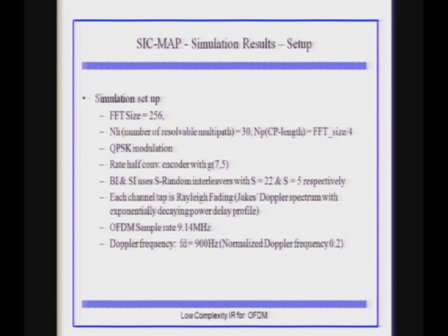And then there is some research that was done on how we can optimize the interleaver so that you can have a balance of the interleaver length and the randomness. You need that randomness because you need the LLRs between the iterations to be independent. If you can design a very good interleaver with minimal delay and sufficient independence, that'll be a great thing.